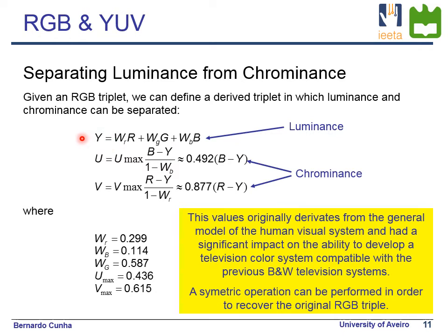This means that in some situations, some visual systems will take advantage of that, and for each pixel, it will send the computer a Y value, but it will only send one U chrominance value for each 4 adjacent pixels, and only one V value for 4 adjacent pixels.